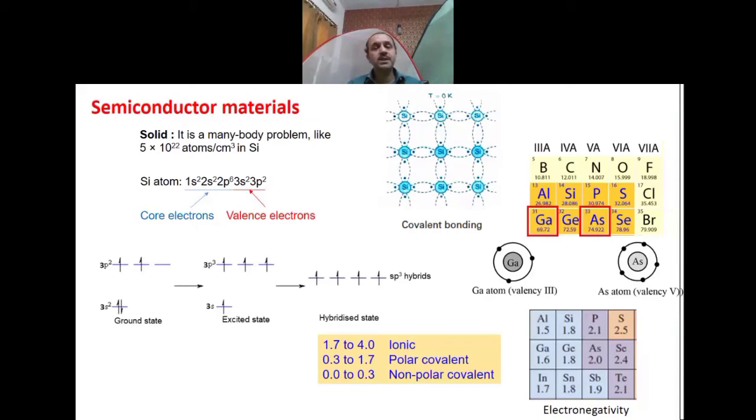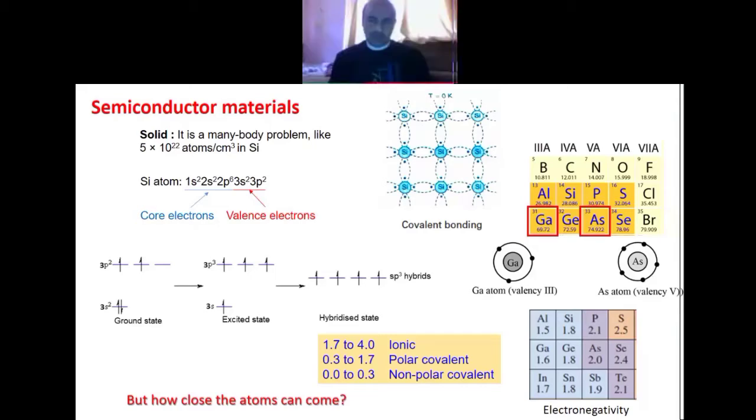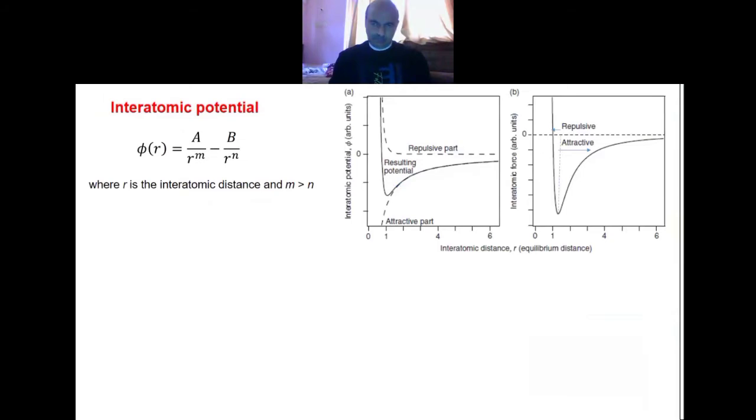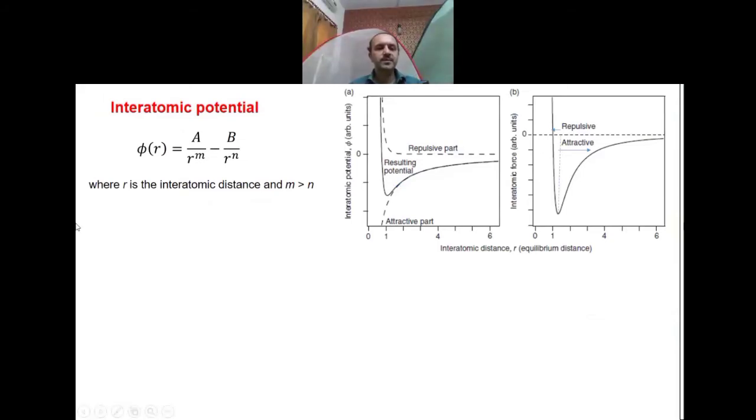That's why in those cases lithography is very, very important, because then you can precisely align your contacts along a particular direction and measure the resistance along that direction. Then you make the contact along the other direction, maybe perpendicular, and measure the resistivity along that direction. So you have to know initially how your sample is oriented, and accordingly precisely put your contacts using photolithography.